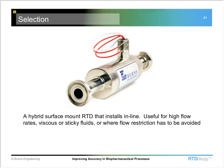And this would really only be used where you have really viscous fluids or stuff that would accumulate around an immersed sensor and build up. So it's kind of a limited usability for high accuracy measurements, but it is an option where an immersion style sensor cannot be used.